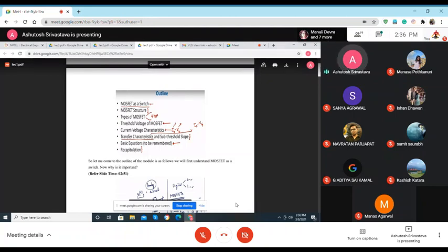And the other important thing why the BJT could not make it, again, I will not go into details, I will just give you very salient points why BJT could not compete with the MOSFET type of transistor. There were two major reasons. First, it was very leaky. So there was a lot of leakage current that was happening. So it was very bad.